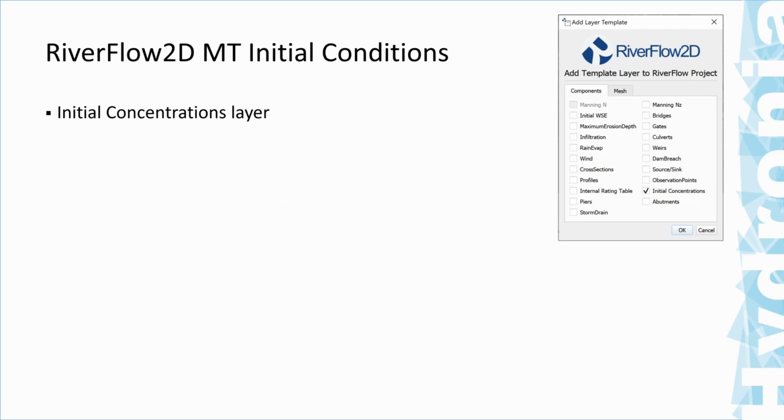So one thing that is very important in the applications of tailing dams is how to establish the initial conditions. Now, in the QGIS environment, we establish the initial conditions. We have two different sets of the initial conditions. One is the raster initial conditions that you use for the actual surface or the elevations of the deposit that you want to model. And then you have the initial concentrations of that deposit.